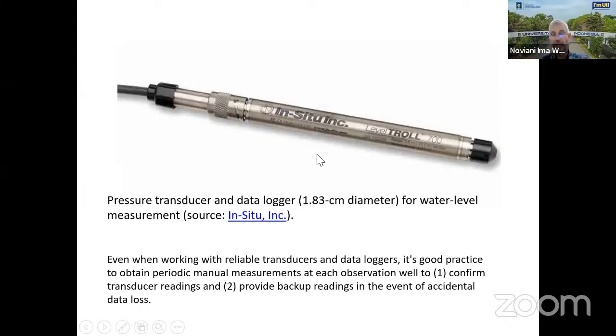And that's, of course, great, because now you can go to sleep for the 24 hours waiting until the test is over and not sit there next to the well and do these manual readings. Instead, you have this automatic logger do this for you. So these are very interesting, very powerful instruments. However, they're not cheap. In America, they cost about $1,500 per instrument. But they help to cut down personal cost, and also you get much more information instead of doing it by hand, as I showed earlier.